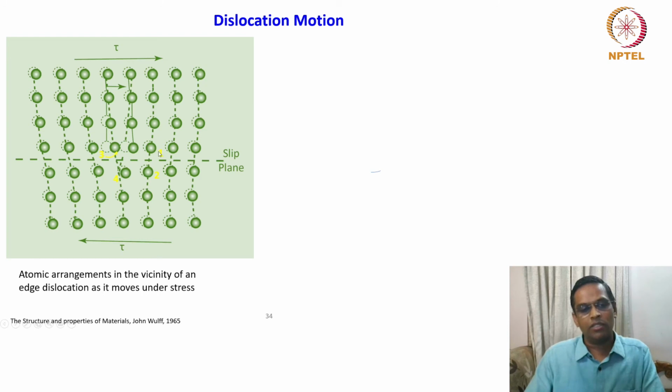The elastic strain energy stored in this atom when it tried to move is balanced by the external stress, and the same elastic stored energy restores atoms 2 and 4 to their equilibrium position. Then this atom will try to move.